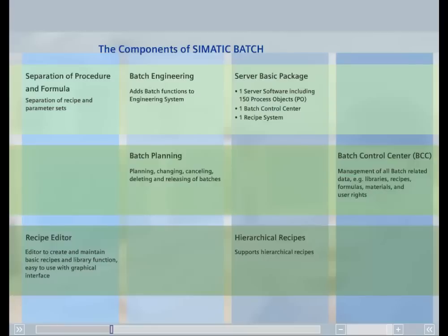User-created recipe operations, known simply as ROPs, can be administered conveniently in a user library or ROP library. These library recipe operations can be included in recipe procedures as references and can therefore be modified centrally. This reduces the effort for master recipe engineering and validation.